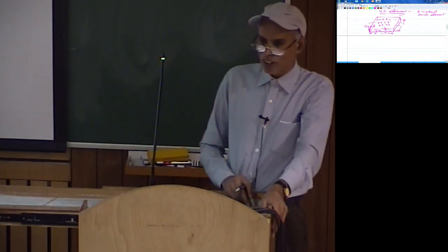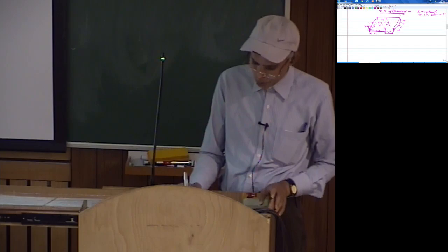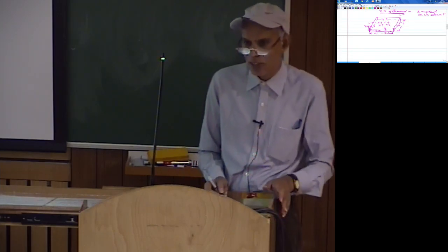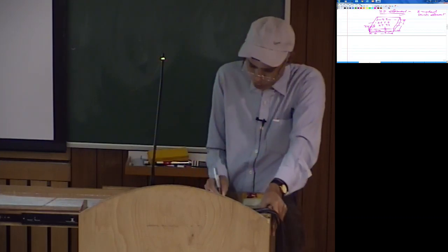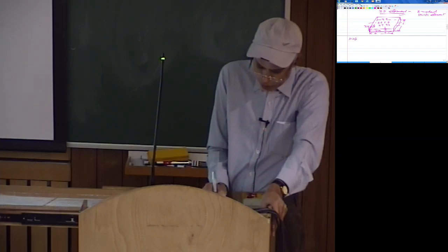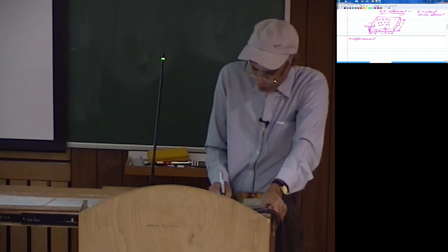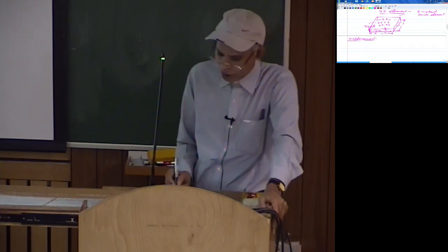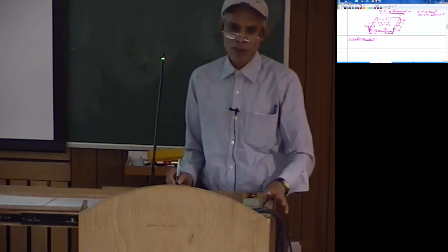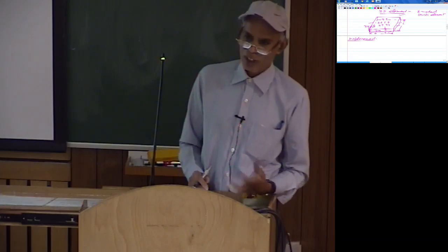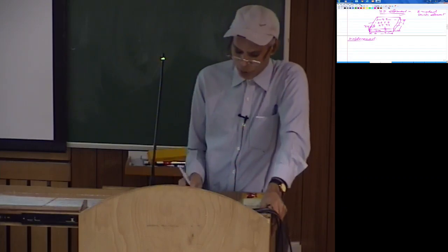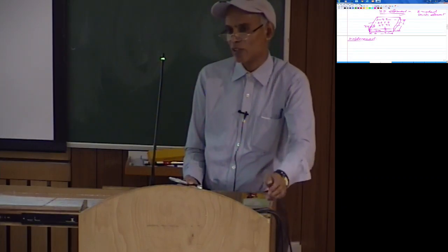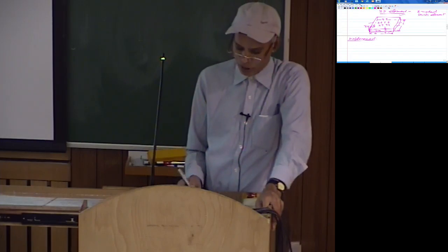Now again, depending on how thick the plate is compared to the in-plane dimensions and what the materials are, there are different plate theories. If you look at the modeling, we are concentrating mainly on the displacement based formulation. Of course, when you do advanced courses you can also learn about the mixed formulation, where not only the displacements but also some stress quantities are degrees of freedom in the formulation, for example pressure in case of hyperelastic and elastoplastic formulations.